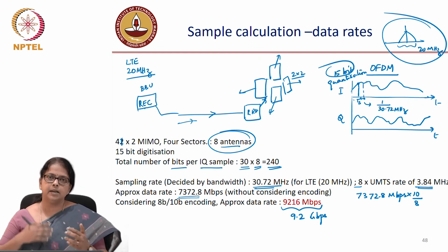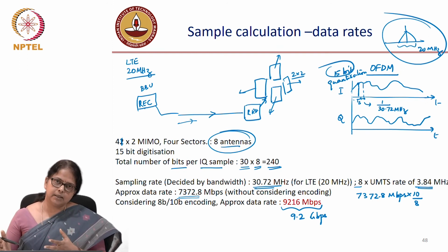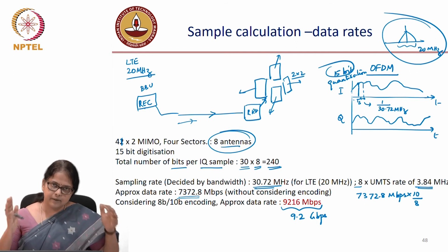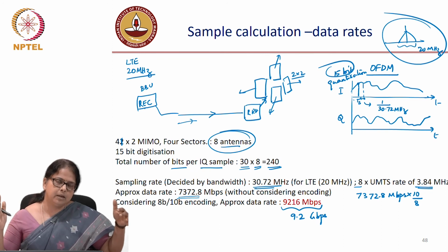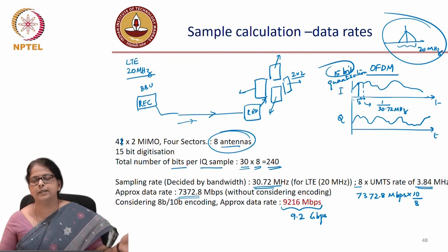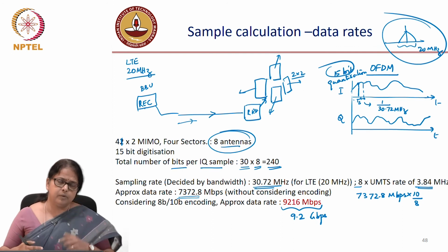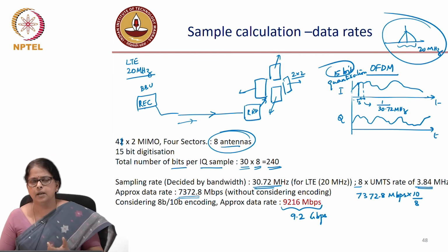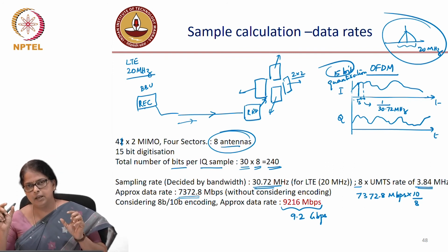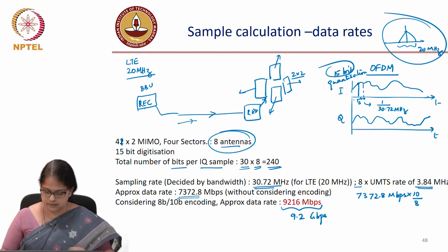And this data rate is only going to progressively increase, which means that the technology required at the front haul, for short distances, anywhere between 100 meters to a maximum of, let's say, 2 kilometers, is where you need a lot of active optical cable research. You cannot really think of using very complicated signal processing in the optical domain, simply because the power consumption in each of these mobile towers is going to increase just because of this, right?